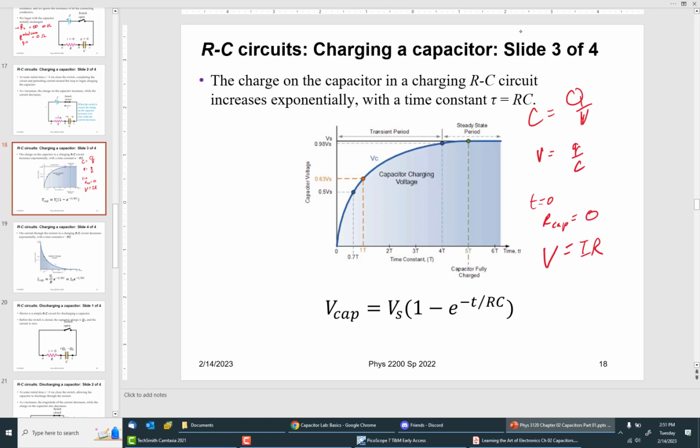Now, this document was written by engineers, for engineers, RF engineers, and so this graph reflects that important stuff you need to know. So the time constant is the resistance times the capacitance, and it has to be ohms times farads. So you have to be careful about microfarads. It's simple: if it says 6 microfarads, then it's 6 times 10 to the negative 6, right? And that will come out in seconds.